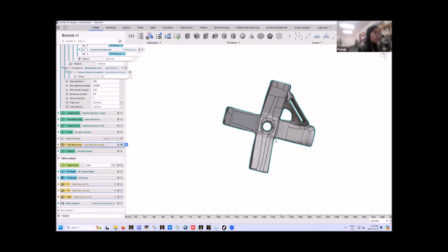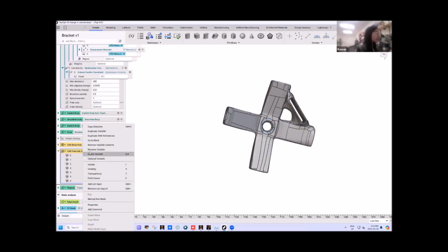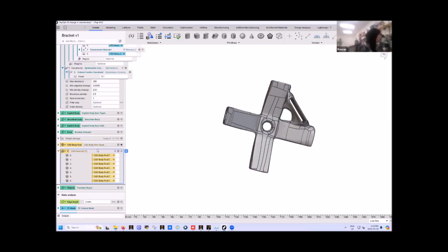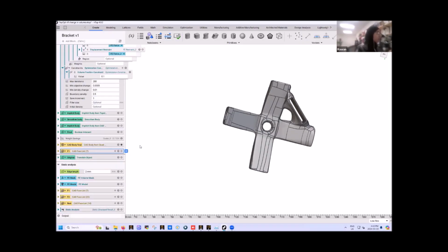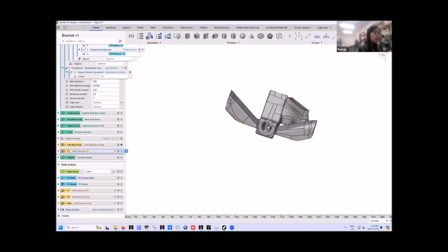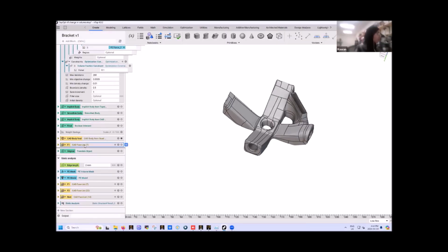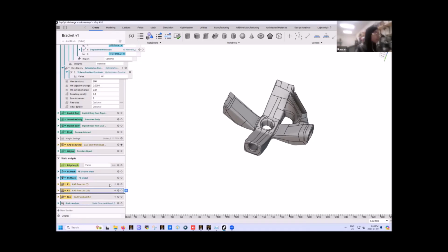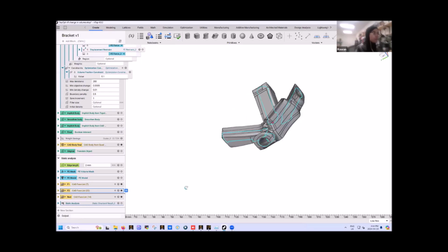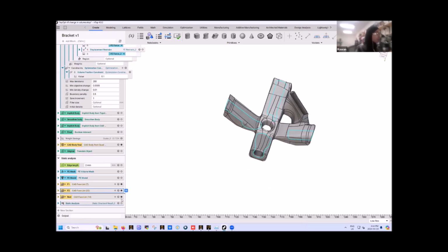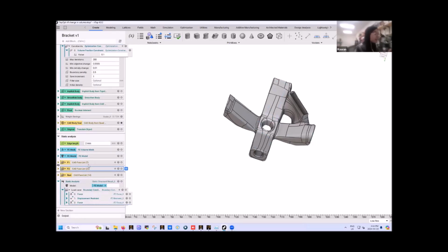So I'll have these ones to refer to the first force. Create a CAD surface. That's force 1. And then I'll go to these parts. I'll repeat the process again here and here. And in the end, I'll have these 3 parts. Not the forces, but the boundary conditions. These 3 boundary conditions, and they are here as CAD faces, like a CAD face list.